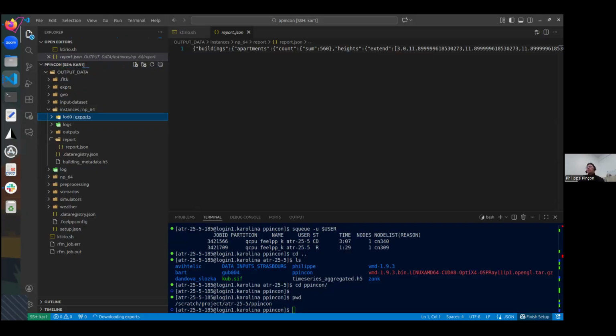For this short simulation, it should be fine, but when you are running very long simulations of big cities, we prefer to download the exports and the visualization results at each time step to be sure we don't lose anything, because it can be really hard to download a ton of data like this.